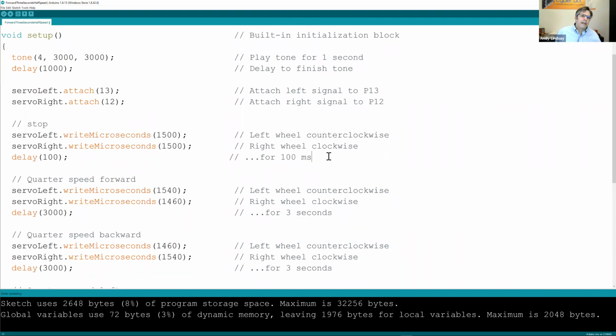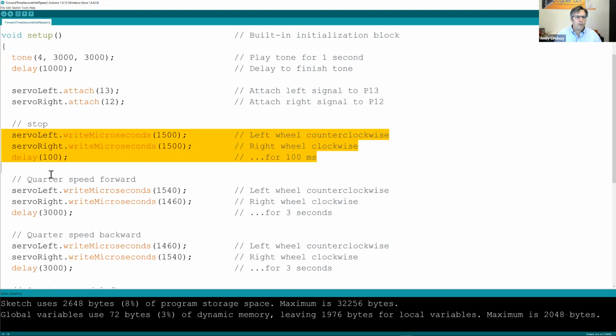The way that servos on model airplanes are controlled is there's a transmitter and it sends radio bursts at a particular frequency. At least the old school ones did. It's gotten to be a little bit more elaborate now, but these are an older model of servo that takes a nice simple protocol where basically the amount of time that the radio burst lasted would cause a standard servo, which is the kind of servo that turns to and holds a position, to position, say, an airplane flap or a boat rudder.